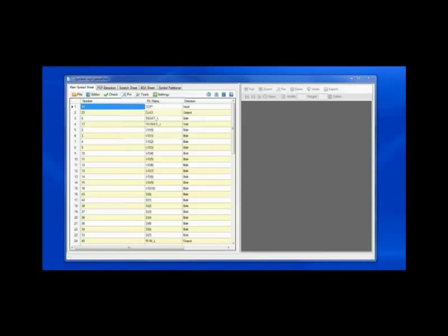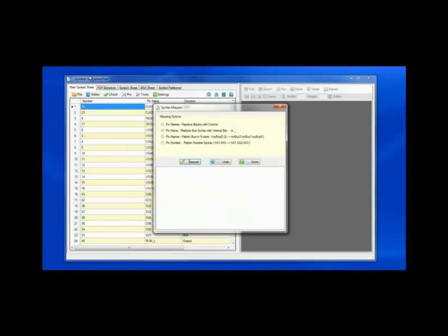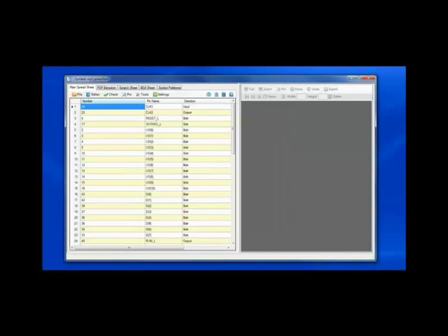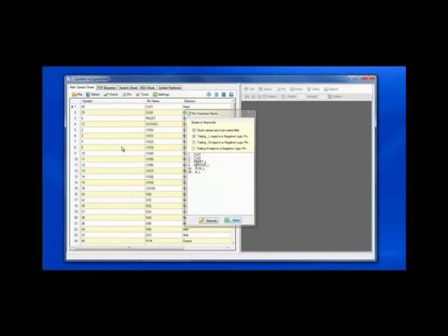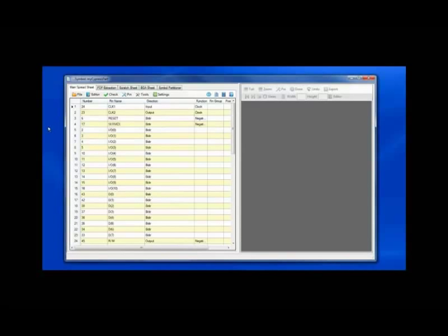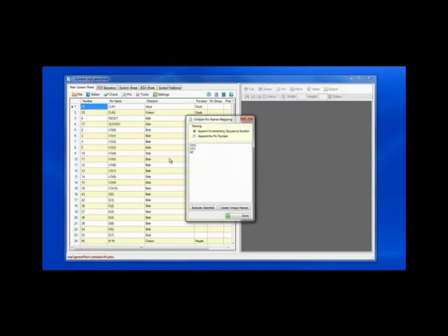But first, let's talk about some of the additional capability. For complex microprocessor data sheets, special handling of syntax, such as in the Freescale data sheets with multifunction pins. In this case, I will automate the clocks detection and in negated logic. And you'll notice when I invoke the function that I automatically detect my clock pins. I can also create the unique pin names at this point, with VDD, VSS, and NC appending a pin number or a sequence number.